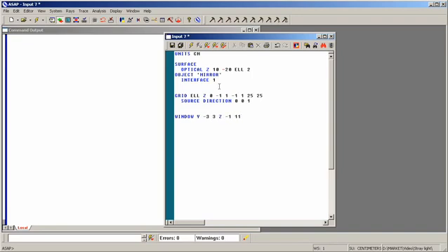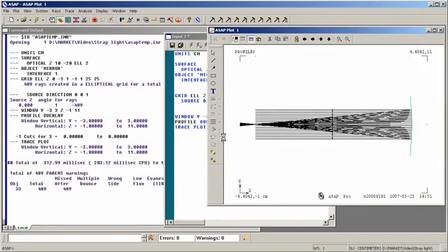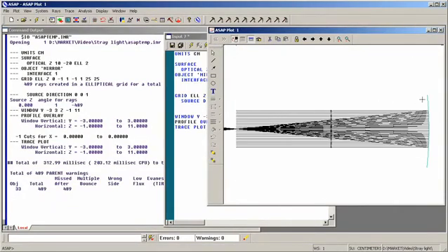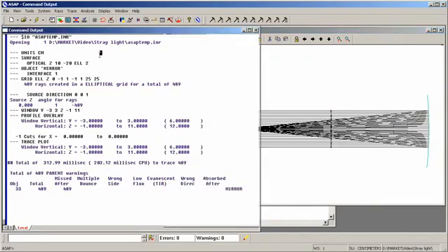A rectangular window with the vertical axis being y and the horizontal axis being z. Profile, overlay, trace, plot. Okay, go ahead and do this. Execute. Here's our ray trace inside ASAP. We zoom in here, we see our collimated rays coming up to the mirror, shown in green, reflecting off of the mirror, coming back down, and coming to focus. Simple geometrical optics calculation.